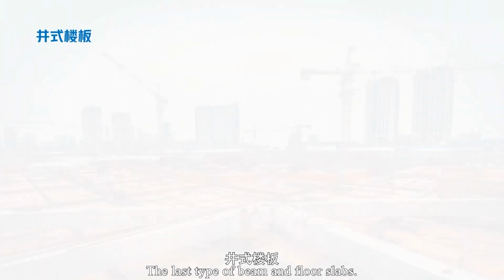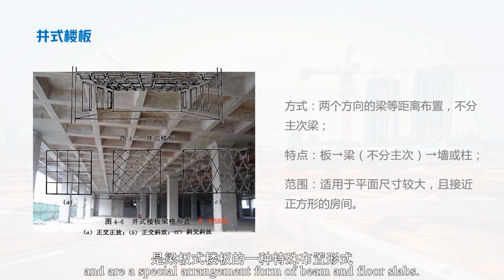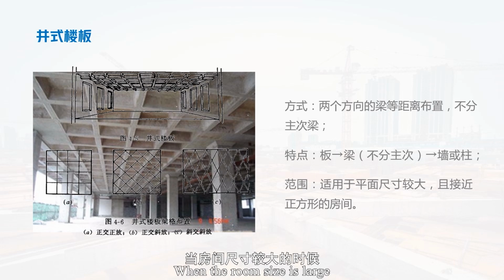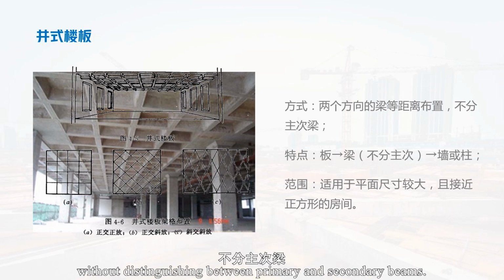Waffle slabs, the last type of beam and floor slabs. Waffle slabs belong to the category of beam and floor slabs, and are a special arrangement form of beam and floor slabs. But when should we use waffle slabs? When the room size is large and close to a square. Arrange the beams in both directions at equal distances, without distinguishing between primary and secondary beams.